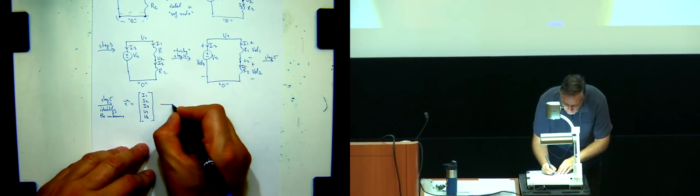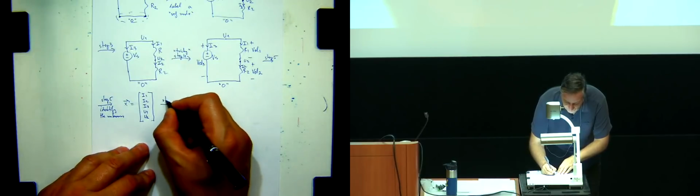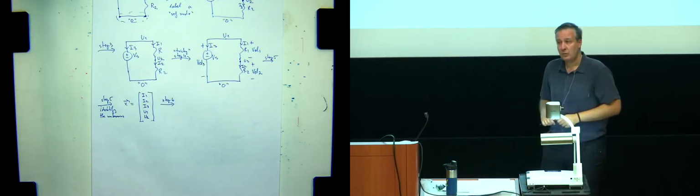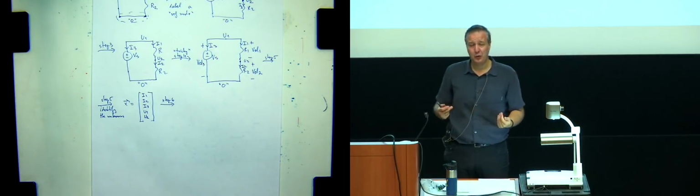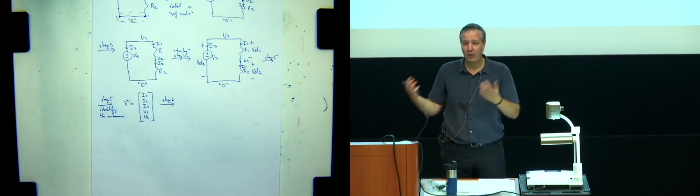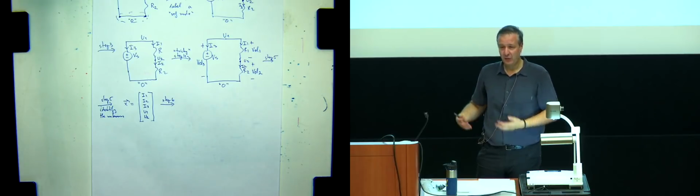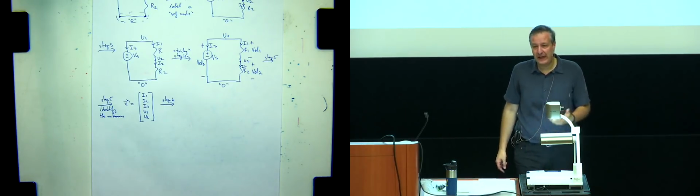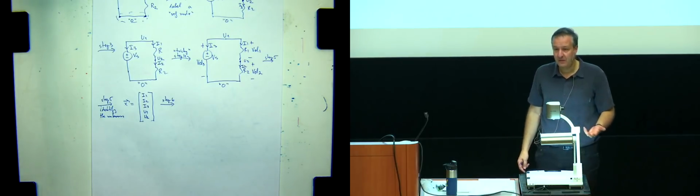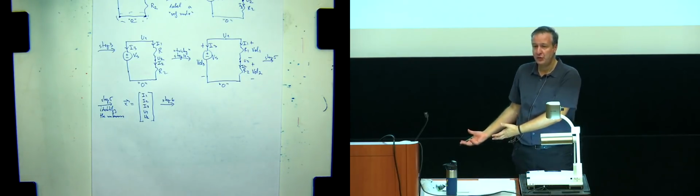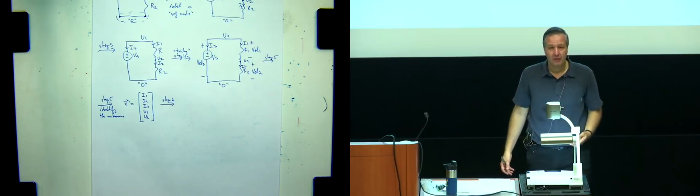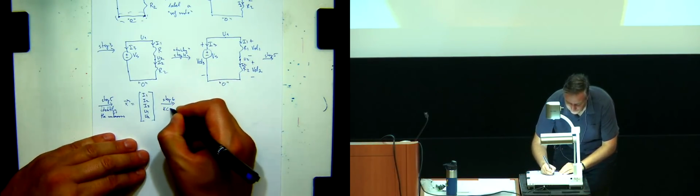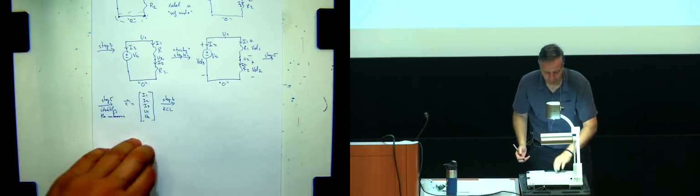Okay, so now step 6, we have to start populating the matrix. At this point, you can choose to use one or the other method to populate the matrix. We need both. Last time, and normally, we use KCL as the first set of equations, but you could also use the element IV first. It depends what you like. But let's say we do KCL here.